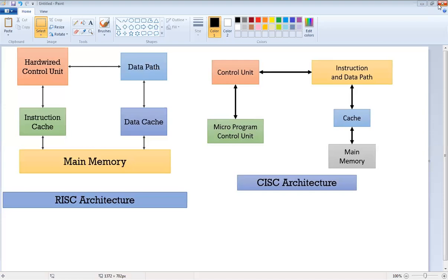It has 8-bit and 16-bit, two types of timers. The PWM output, that is pulse width modulation output, is generally useful in motor controlling operation to control the speed of the motor. Then analog comparators, inbuilt comparators, are there. The 10 or 12-bit A to D converters are there, with multiplexing up to 16 channels. It means 16 inputs can be connected at the same time. It has a 12-bit D2A converter also, digital to analog converters, and it can give analog output to drive the motors or some displays.